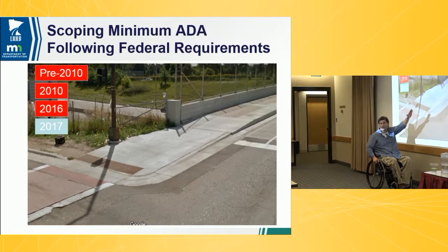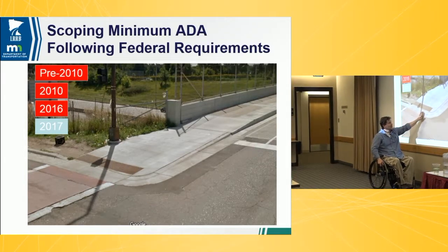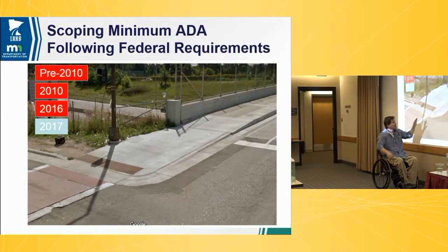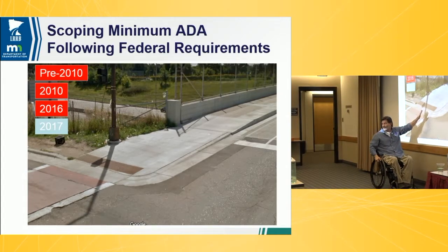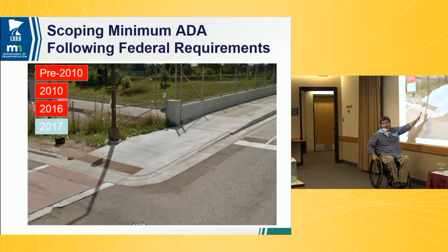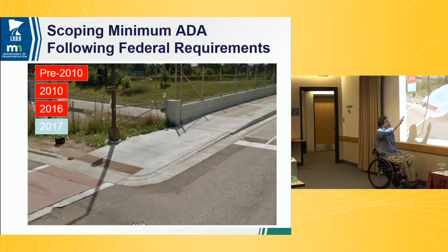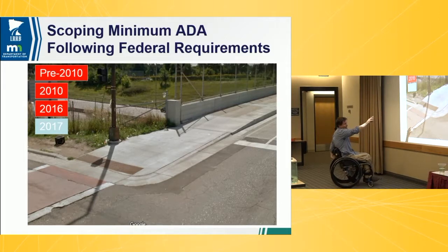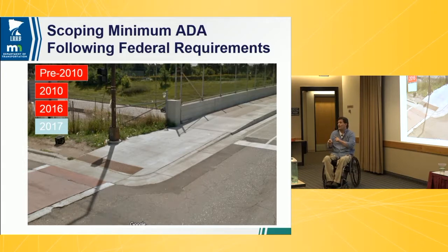And again, we're still too steep. So some of the answer is, we've got to raise this flow line still. I've already taken the 4 inches off the top, but I need to get another 4 or 5 inches out of this curb line. Again, because it's too steep, but also there's no APS here yet, and there's no landing if there would have been a button. So okay, we'll just keep waiting for the right project. We'll keep doing this piece by piece.